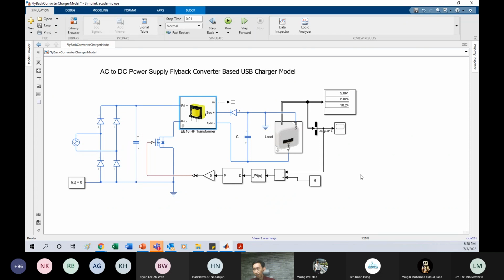It's a very rare power supply that uses boost, because you already have 330. What you need is 5 watt, so you don't do boost, right? It's either buck or this flyback. And of course your important factor is your PI, right? Your PI control must be good enough.